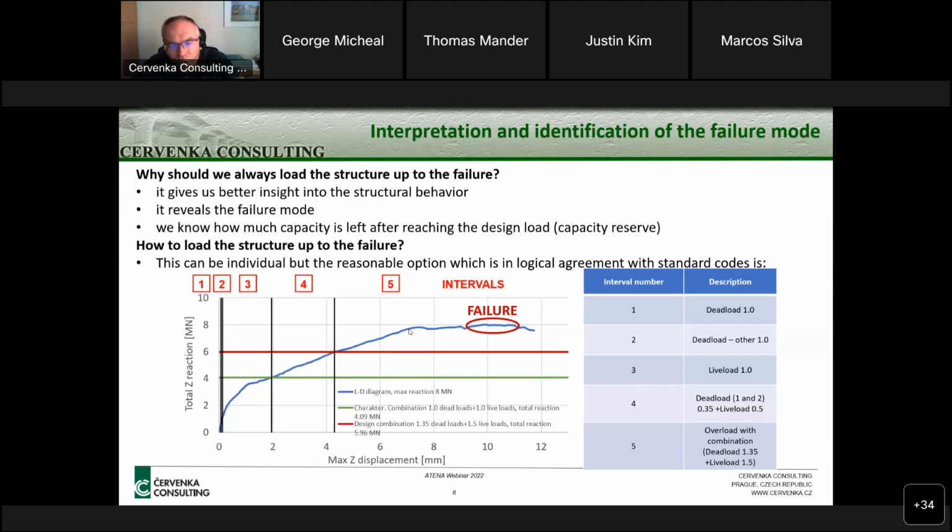I don't want to discuss here what the arc-length method is about technically, but let's just say that even when we apply loads as forces, it allows us to detect that there is a peak load, and at some point the program automatically starts decreasing the forces.